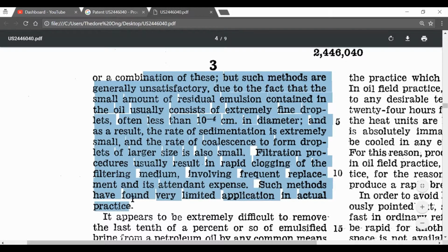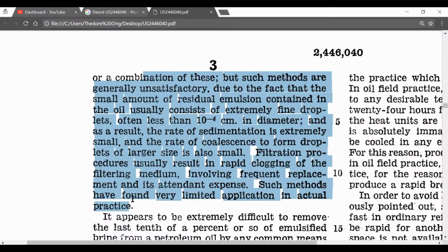So here they're telling you to get out the residual percent. So okay, let's put it in numbers. You have a crude oil that you drill out of the ground. Maybe it contains 3 to 4% of water and salt content. To make it available for the pipeline, you want to push it right down to 2%.